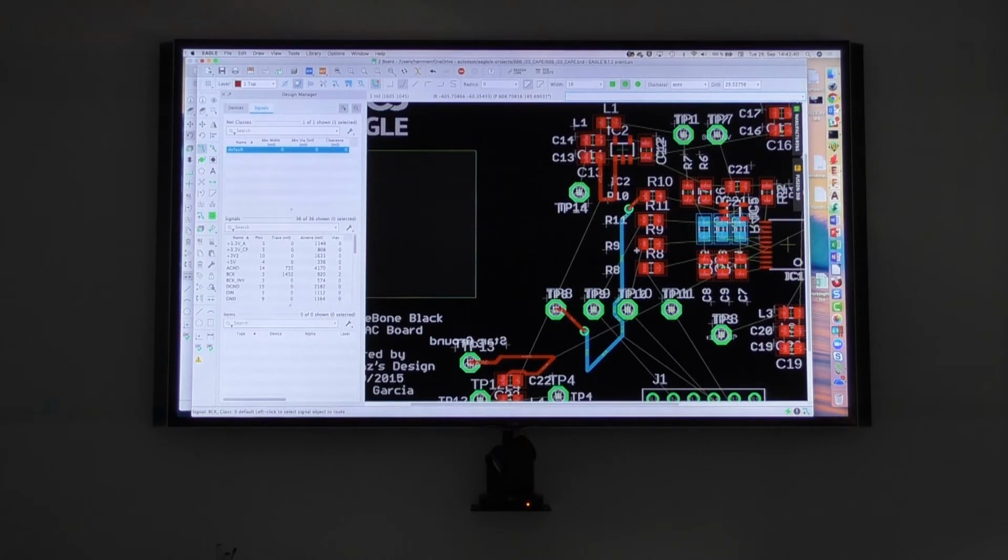Can you not do that with the space bar, to change the layer? Yes, that's possible. I click onto this one, I start in the top layer, and now I can hit the space bar. I get the next layer and then I can go on. I can only click from one layer to the next, but if you're just doing a two-sided board, the space bar works. I think it should also work the other way.